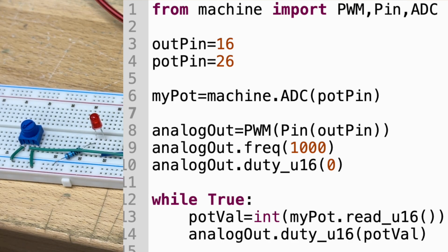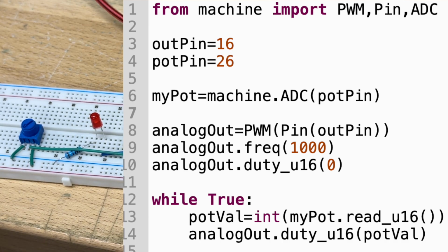And that's because this is pretty handy. Our ADC and our PWM are both unsigned 16-bit integers, which means they both have a range of 0 to 65,535. So no conversion necessary. They should be a 1-to-1 match. So we can just drive that value straight to that LED.